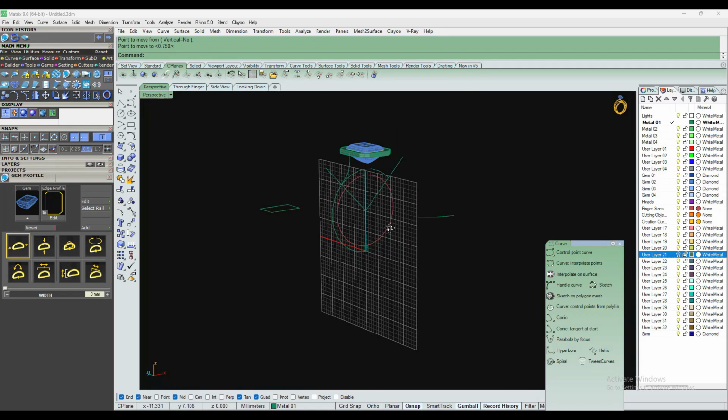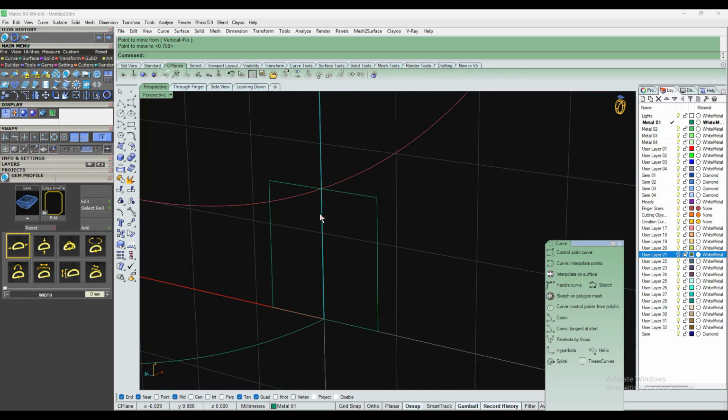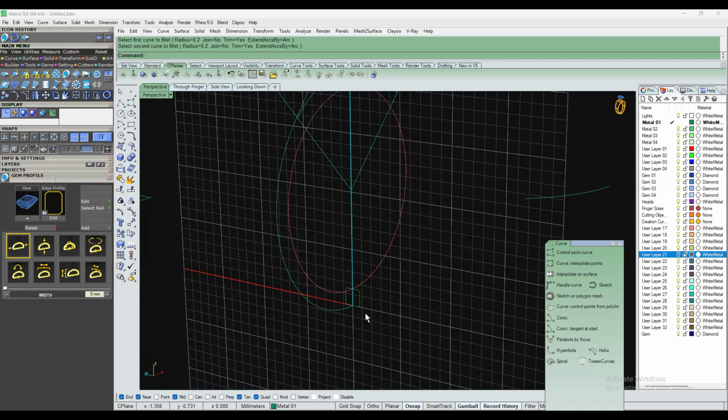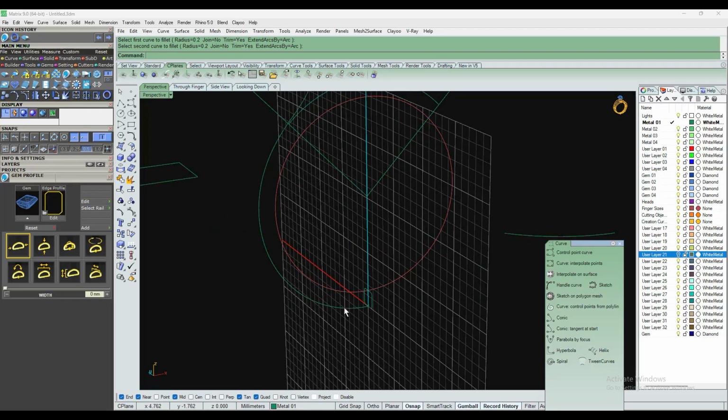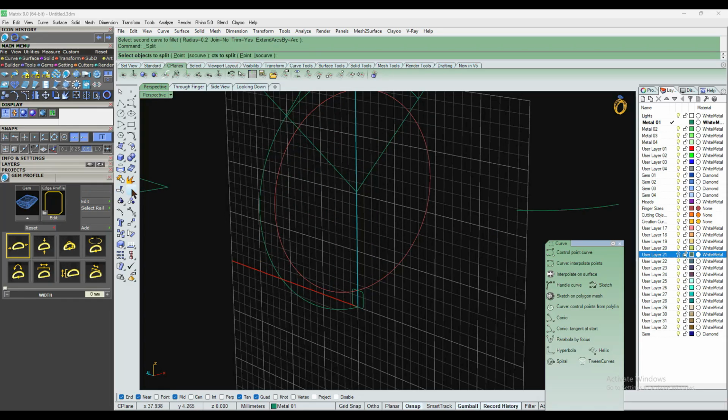Okay, we already have specified this 1.5, so we need to use this as a 1.5. Here is the fillet option, and you can specify your radius as 0.2. Make sure you are using a proper fillet value, otherwise it will not create any fillet. Okay, now this curve is going here, and from here it is going to split. So specify any split point, and you need to select your curve, then use the split option, click here for a split point, and you can use your proper point. Let's use this point for a split point. Okay, this is our split point.